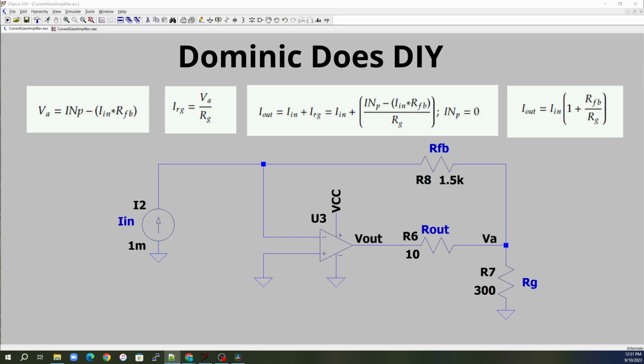The voltage at the output of our op-amp is just going to be VA minus our output current times our output resistor. When we do this, our voltage at the output of the op-amp is going to be heavily negative. So when we went into the real world, things went all squirrely as the op-amp tries to compensate with its working voltages and whatnot. Here we can see it looks good using an ideal op-amp, but when we get into the real world, the simulation doesn't really show us what's going to happen, and that's why we have to go through these calculations.